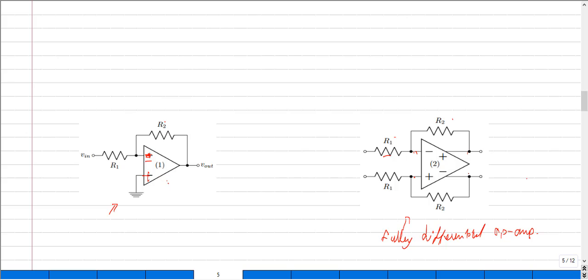Yeah. So now, however, we had a kind of network around this single-ended op-amp. Here again, we need a kind of feedback network around this. But the point here is they have to be in opposite phase with each other. So what we have done is connected our R2 across the negative terminal of the input node and connected back to the positive terminal. So they are actually opposite in phases. And similarly, the same thing happens when we connect this R2 resistance across the positive terminal at the input to the negative terminal at the output, thus creating a kind of negative feedback around this particular circuit.